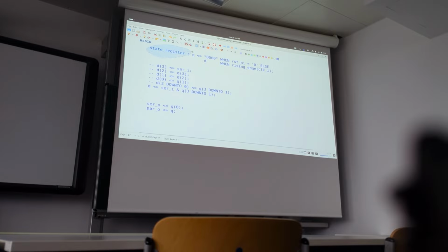The state register, the next state logic, if we say here, this is our next state logic as a label. And these 2 lines as a comment are our output logic. We still follow our synchronous logic block design. So again, 3 blocks.